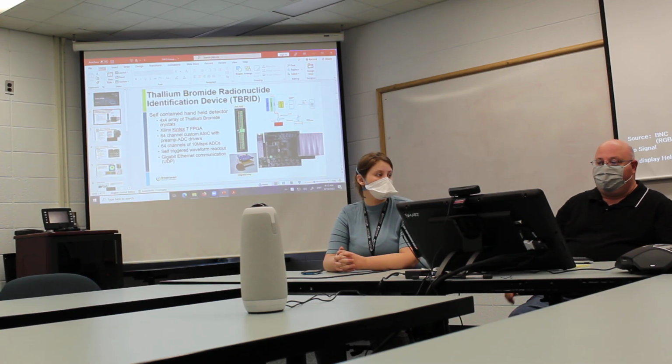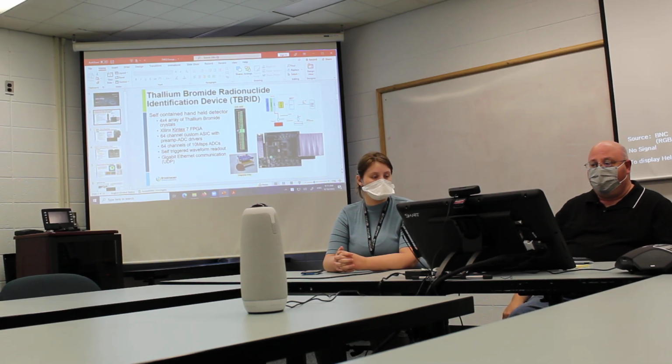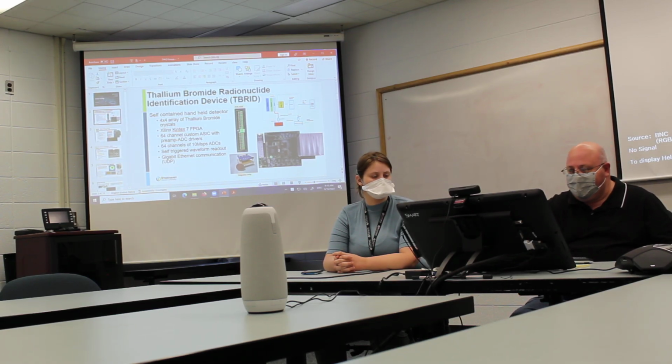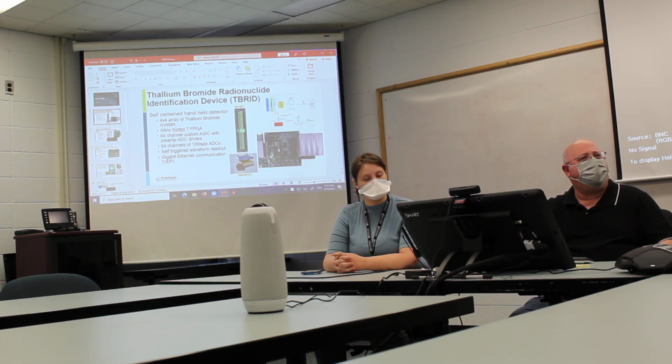So here my group developed this readout board, which is using a Kintex 7 FPGA. It has 64 channels running at up to 80 megasamples per second. I think in this case we're only running at 10 megasamples per second. So it's two ADCs connected to a FPGA using, I don't know if you guys are familiar with the JESD204 standard. It's a high-speed data link using transceivers.